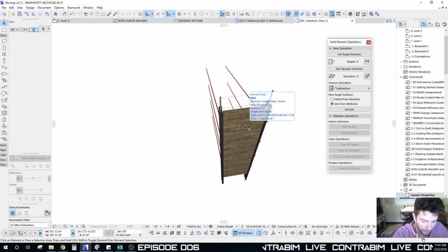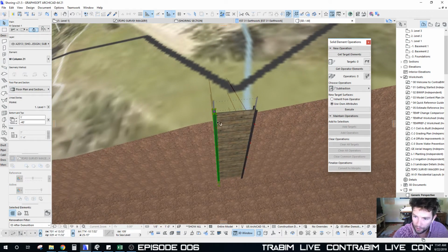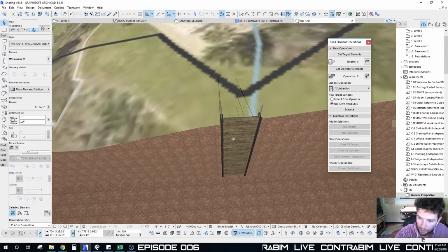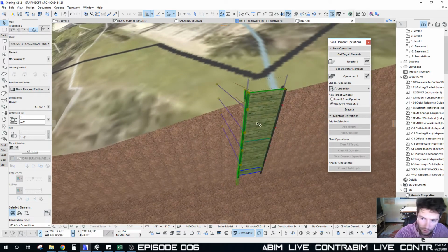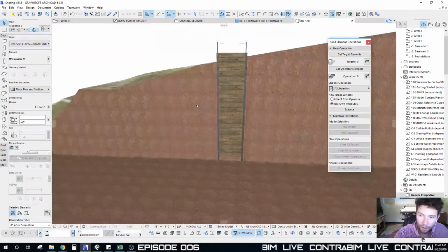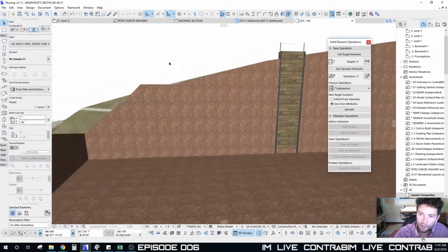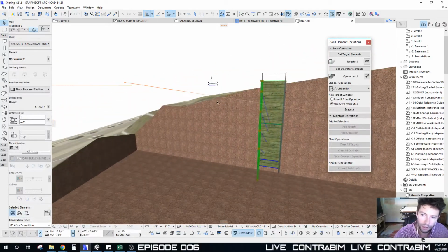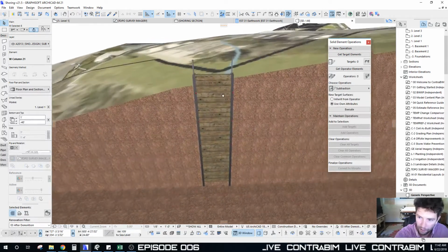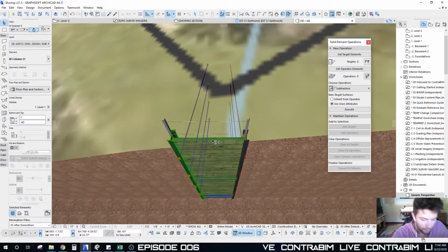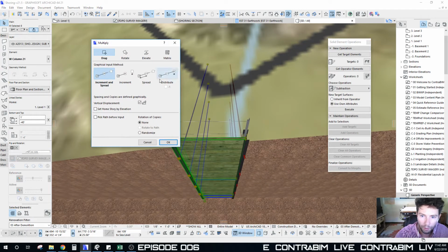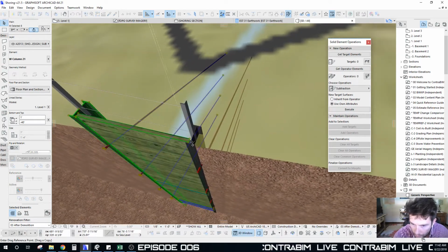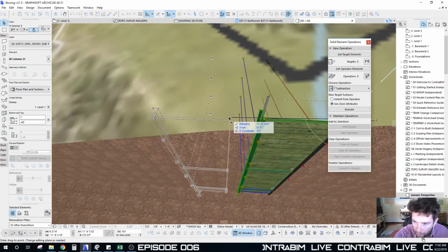And we'll bring back everything. And so now I'm going to grab these, and we can really just, because this is kind of dropping down right here, what I'll probably do is pull it over, and then I'll start adjusting the elevations of them. So let's do that. And I'm going to do a multiply here, and I'm going to do an increment and spread, and I'm going to leave on my vertical displacement here. So let's just come in and start from that point.